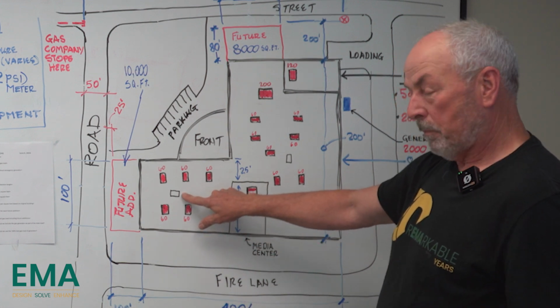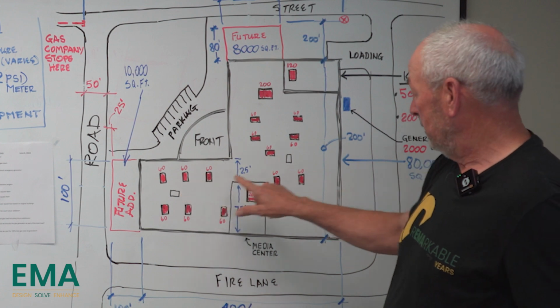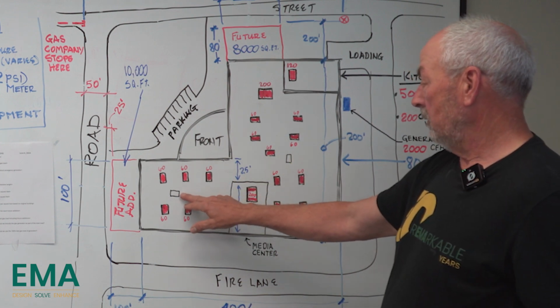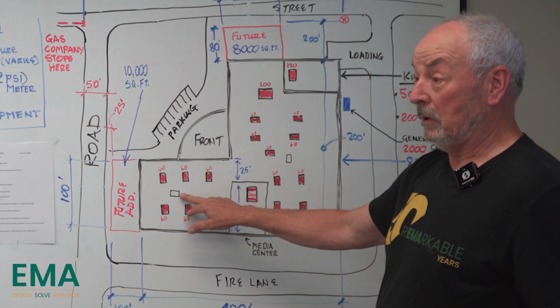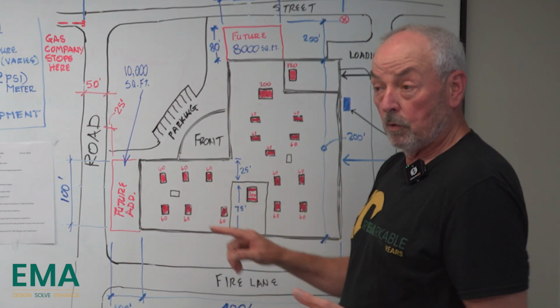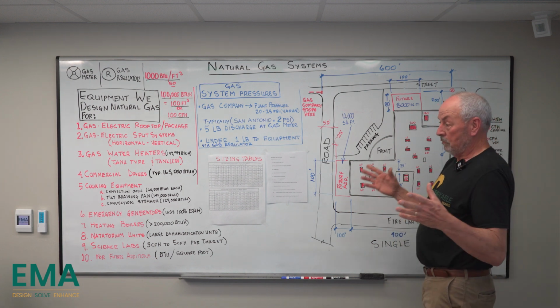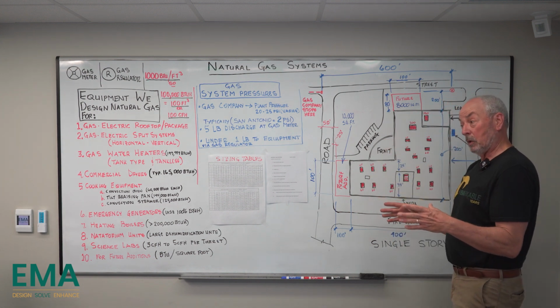These are rooftop units. And then I purposely left this one unshaded for a reason. These two right here. These are cooling only, so there's no gas load. These are usually for electrical rooms, IDF rooms, MDF rooms. We just want to cool. There's plenty of heat in these rooms.